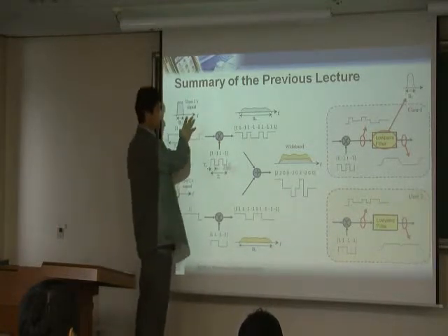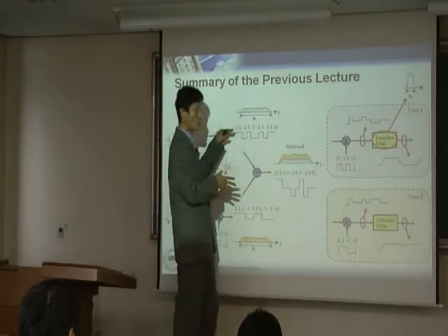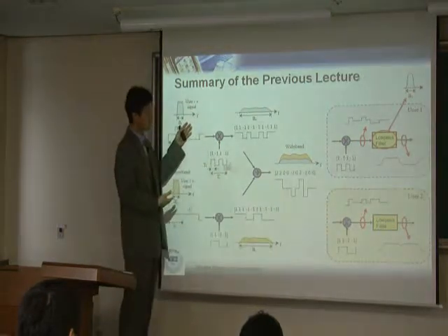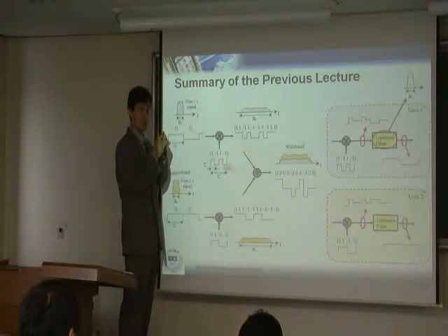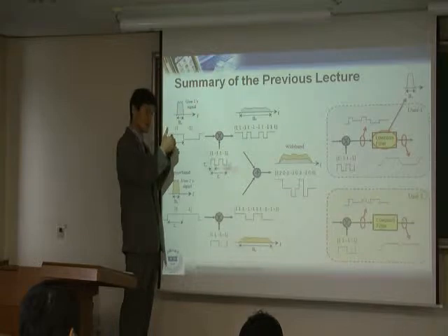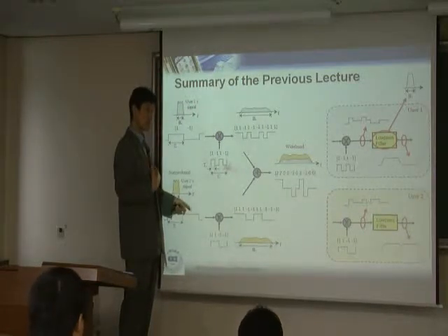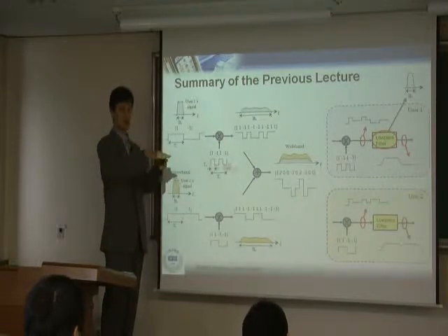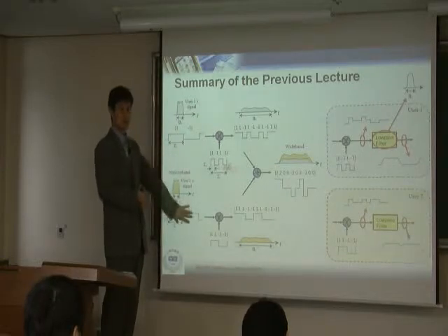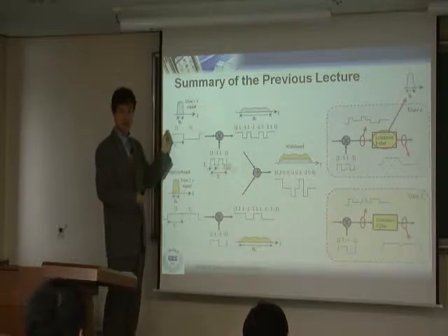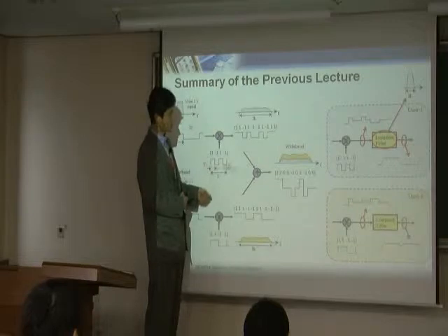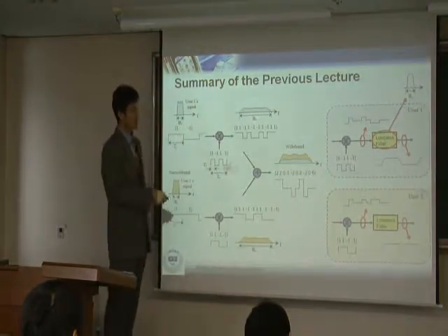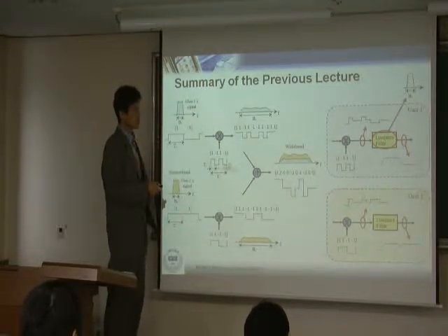Even then, when you transmit some packet, and this guy transmits some packet, those two packets should be received by the base station at the same time in a synchronized fashion. So if this guy is close by, maybe you can transmit a little bit later, considering your path loss, because this guy is close, so path loss is small. But this guy is far away, so considering path loss again, this guy has to transmit much earlier. That way, this guy's packet goes through the propagation delay, not the propagation loss, the propagation delay. This guy has a large propagation delay. This one has a small propagation delay. So considering two different environments, two different propagation delays, both should be received at the same time at the base station.